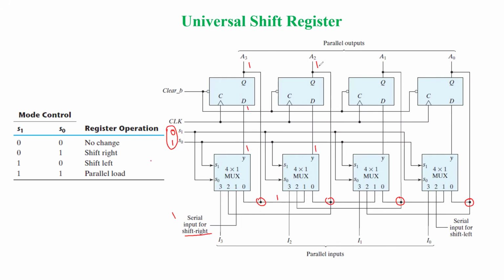Now again the clock pulse changes, and here we have positive edge trigger. This 1 is again the input to port 1 of the next multiplexer, available as the output, and again the same is input to the D flip-flop, and finally A1 is also 1.